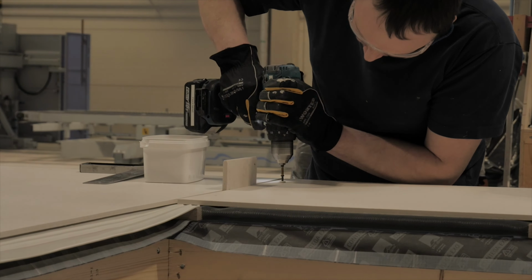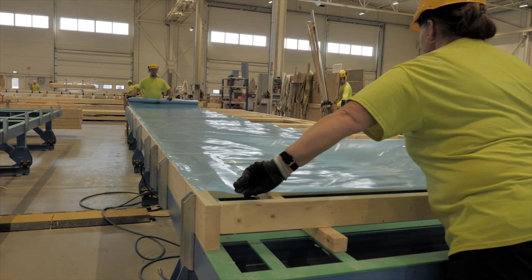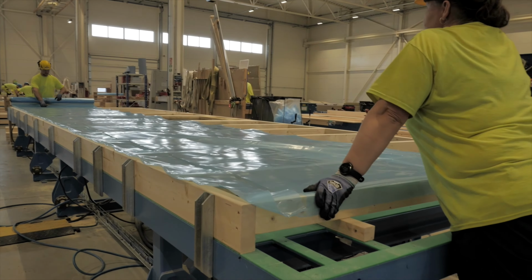When it comes to external walls, in order to prevent the spread of moisture and air from the interior to the wall structure, a vapor barrier should be installed, which in most cases is a strong and age-resistant film. Installation and fixing of the vapor barrier must be carried out according to the solution of a particular project and the typical solutions of the company.